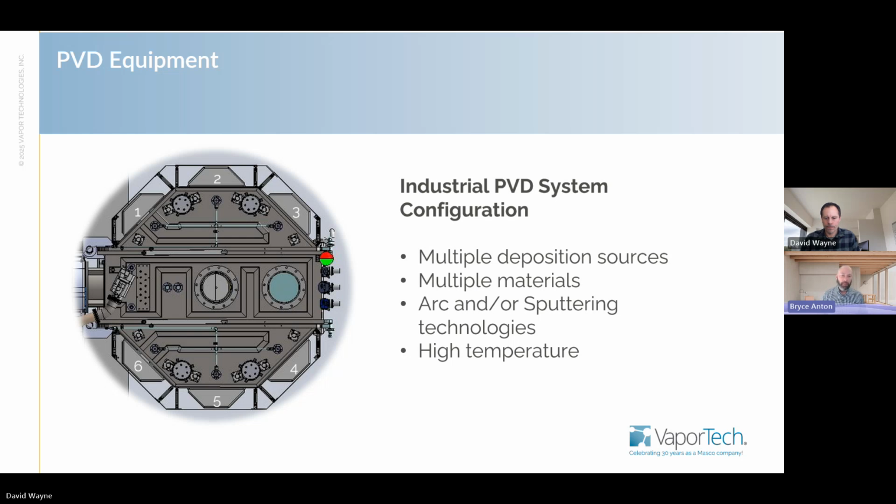Absolutely. So the basics of a PVD chamber is a big vacuum chamber that you put your parts into, and then you have your targets, which are the starting material, the raw material, like we talked about before, whether it's the titanium or the tungsten. And there's different configurations of systems. VaporTech's been producing PVD systems for 40 years, and we've had different configurations. Some of our systems have a target in the center of the chamber that sprays outwards, but our newest product that we're launching right now has those targets on the outside.